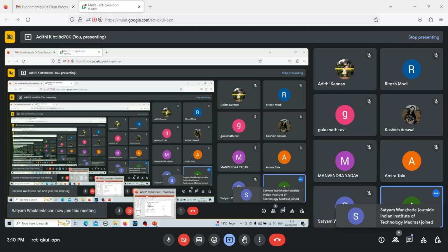So in a Kelvin-Voigt model, you see a kind of mixture of different elements. You have an elastic spring and a dashpot connected in parallel. This entire assembly is again connected to a spring here. Different models will describe different kinds of fluids. So when you are doing modeling, you will need to check which model best describes your fluid based on the kind of data that you have. So this is the Kelvin model, this is the Kelvin-Voigt model.